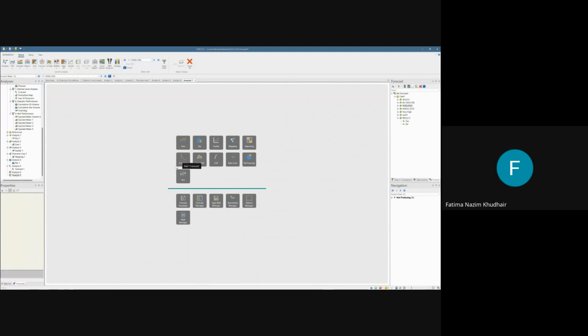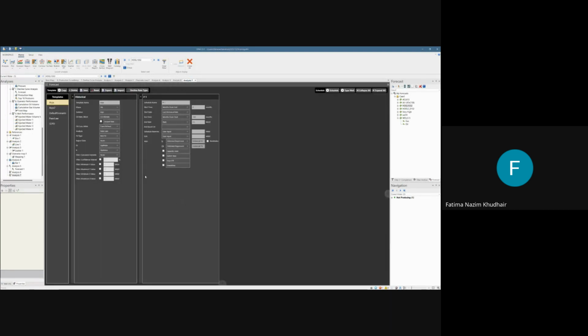Please, I want you to pay attention here. In forecasts, we just open the templates that were already created down here. So in the lower section, you have the reports and the forecast manager. And in forecast templates, let me open it again. Here you will set your method, your phase, your schedule, and the schedule details: from which time you are going to start your forecasting, to which time you're going to end it, and the ending rate and the details of it.